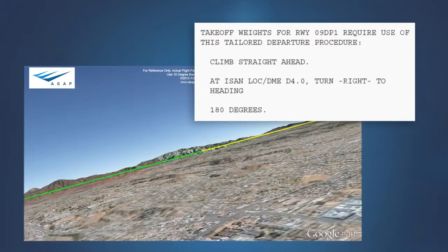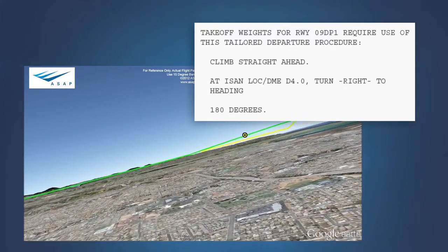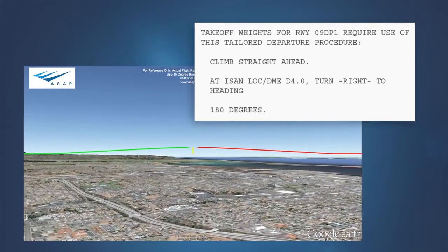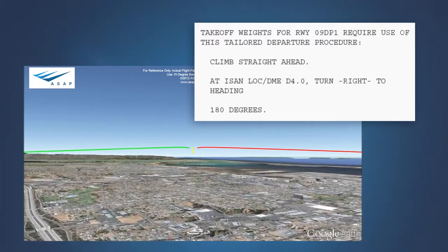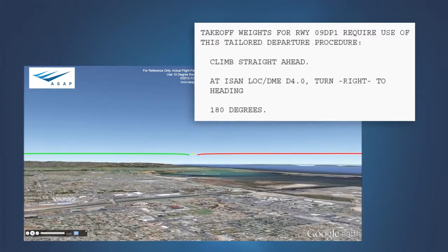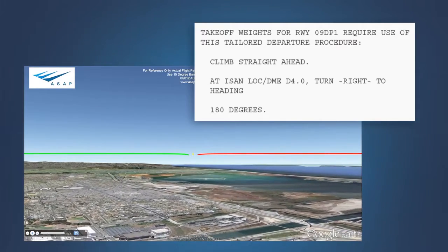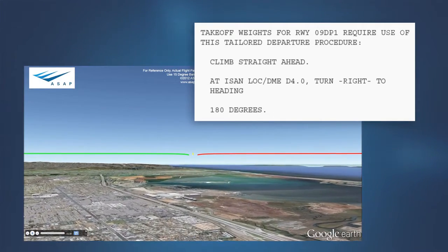The effect on climb performance resulting from the bank angle flown during the turns is included in the allowable takeoff weight limit. Because a turn is involved, the obstacle accountability area expands in width to 3,000 feet either side of the track. The procedure may be defined in simple terms of turns and headings to fly following an engine failure. Ground-based navaids are usually used to identify the point at which a turn is to begin.